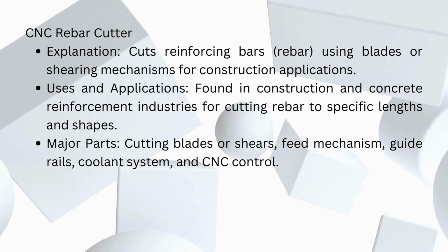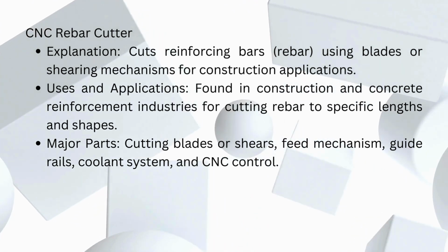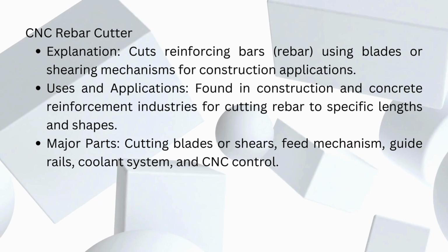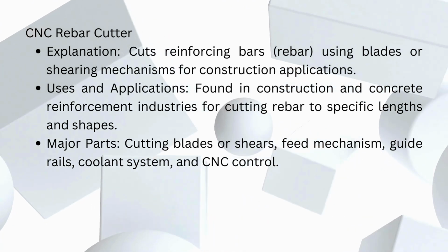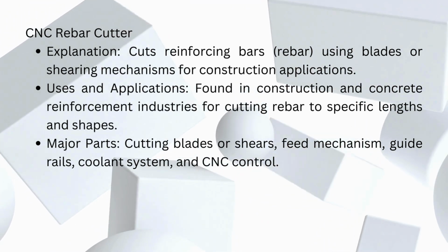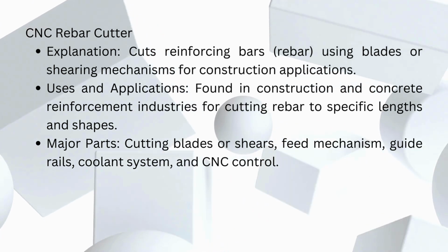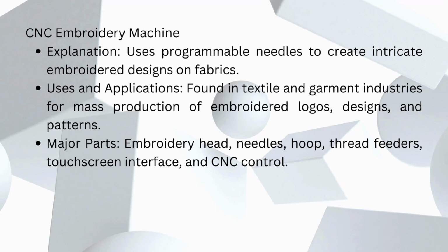CNC rebar bender. Explanation: bends reinforcing bars, rebar, into shapes and configurations required in construction. Uses and applications: used in concrete construction for bending rebar into shapes like stirrups, hooks, and angles. Major parts: bending mechanisms, tooling, guide rails, feed mechanism, coolant system, and CNC control.